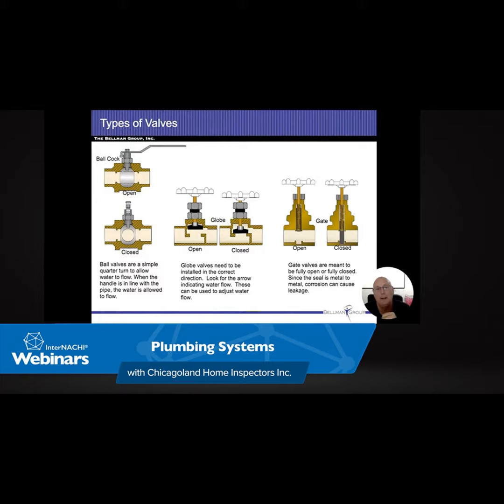In fact, it happened to me a couple of times. I'm pulling off of one hydrant and then another engine hooked up on a different hydrant, and he basically stole my water. So then as I'm trying to draw water out of it, I'm going negative. Anybody that had water spigots open in their houses, I would actually be taking all the water from their houses and bringing it into the water system there. So it would be siphoning. In this case right here where that tub is, if that was happening and that valve was open, I would actually suck all that soapy water and dirty bath water back into that pipe where somebody could use it again at another time.